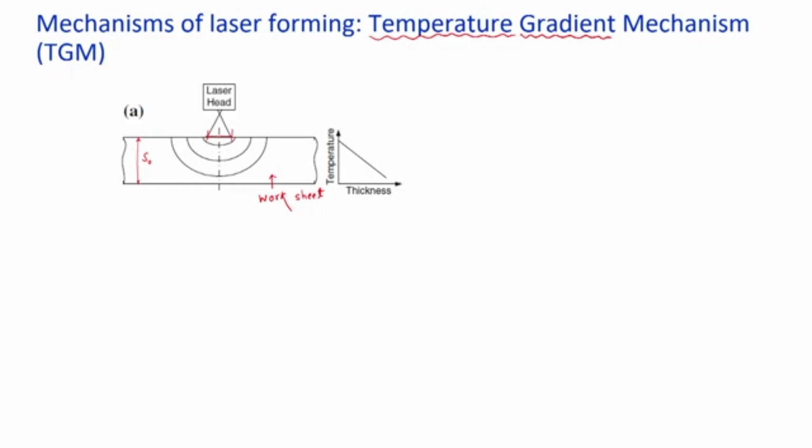If you focus the laser on the work surface, there may be chances of having intense heat generation, and that intense heat may spoil the work part. It may either vaporize the work part or melt the work part, which we do not want here. So, therefore, we are using defocused laser during the forming operation. So, accordingly you have to tune or set the SOD, that is the standoff distance. So, the diameter of the laser beam on the surface is D. So, this is the diameter D.